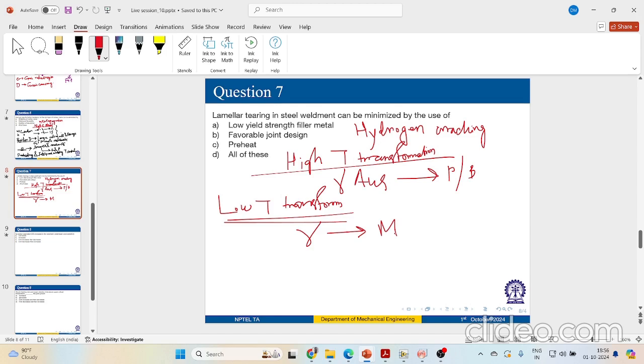So dissolved hydrogen has a more damaging effect in the presence of martensite. If you have martensite in your structure and hydrogen dissolved in your structure, that has a very dangerous effect in your steel structure, right? So hydrogen dissolved in atomic form at low temperature tends to diffuse out gradually towards vacancies and other discontinuities.